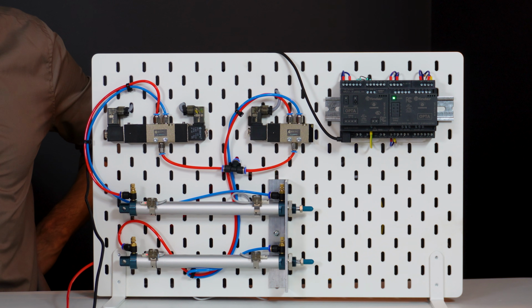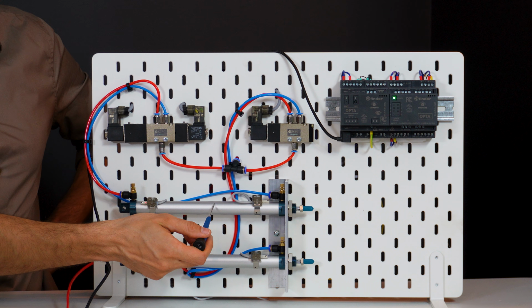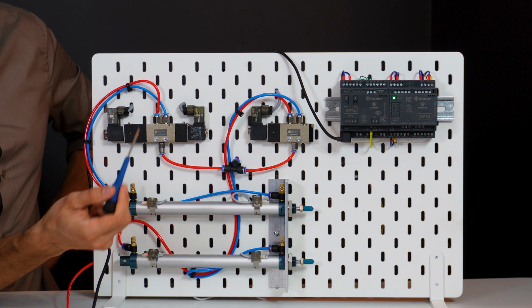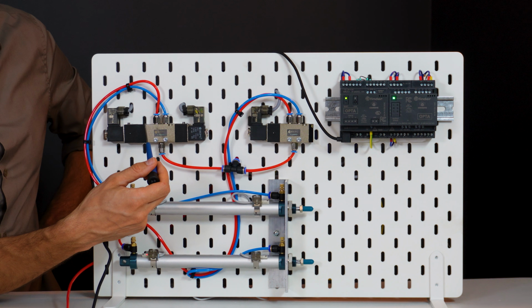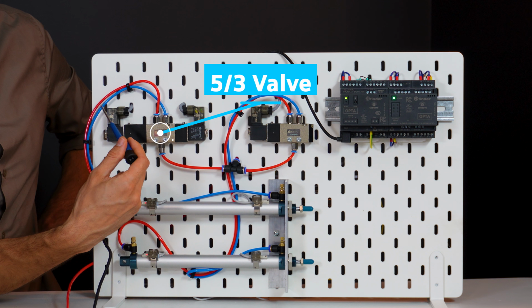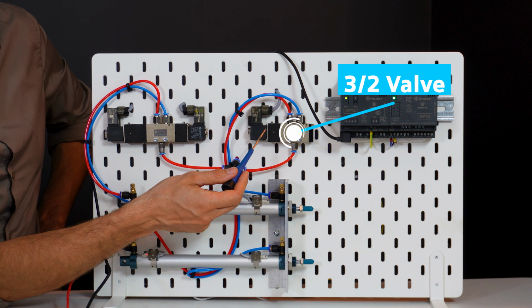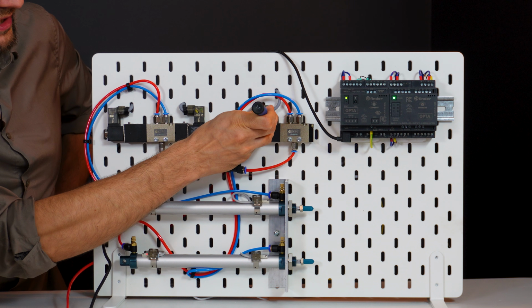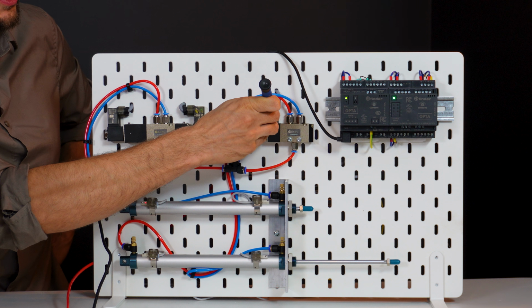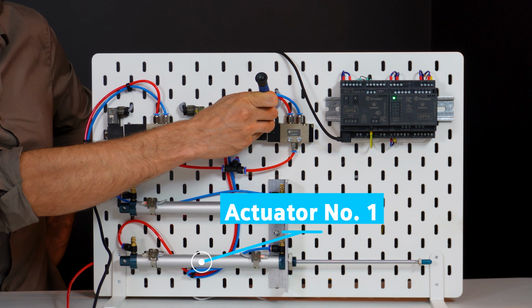Before we start programming in the Codesys environment, a few words about our setup. Look, we have two pneumatic actuators here, which are connected to two pneumatic distributors. One of these distributors is a 3-position distributor with 2 coils. Meanwhile, the other distributor is a solenoid valve with 1 coil. If I manually trigger this solenoid valve, look, the actuator extends. This will be actuator number 1.